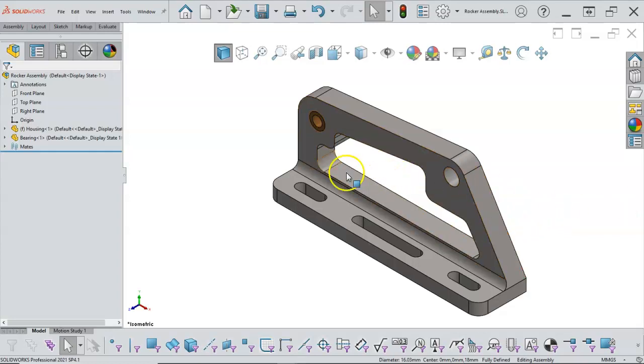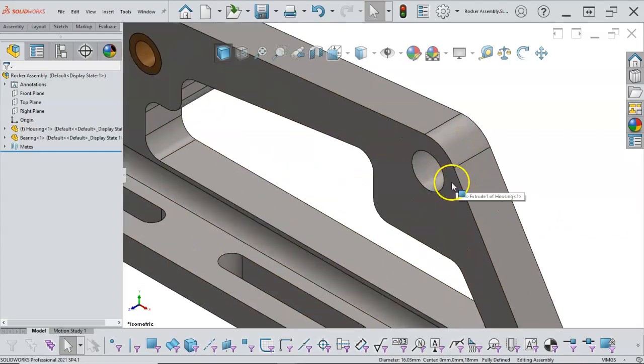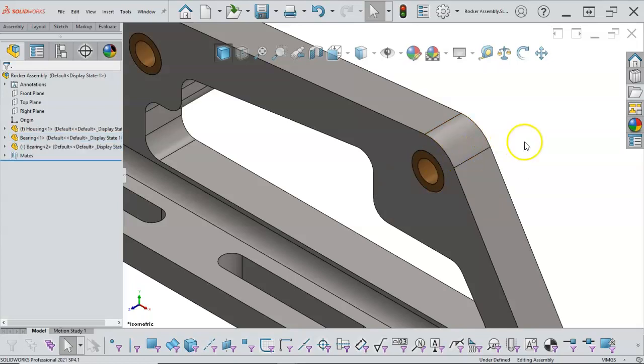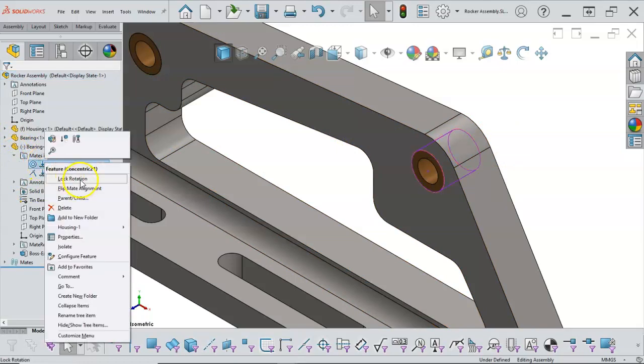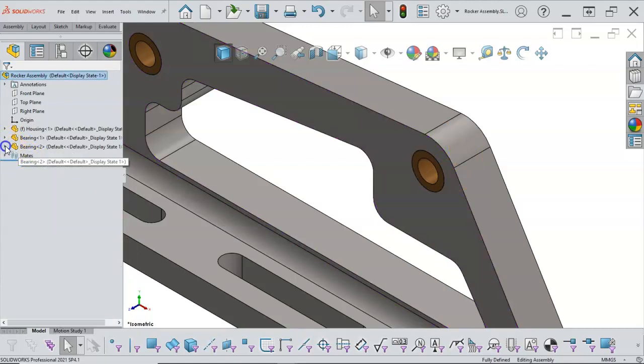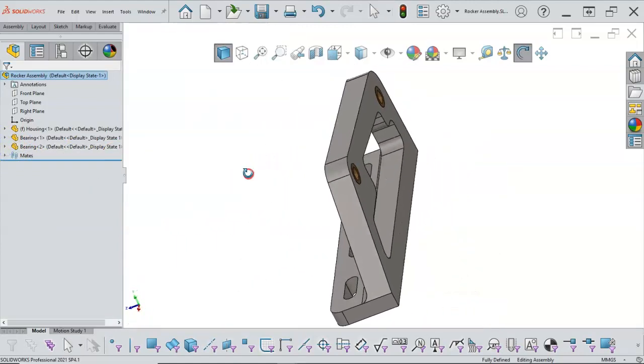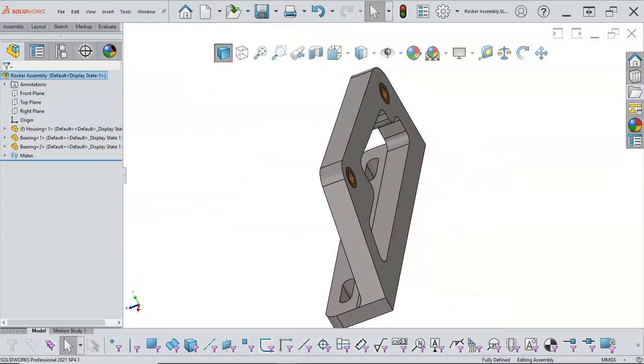just doing a real quick check. All right, so if I hold down the control button and the bearing and drag it to the edge, and this is where contortionist, I actually want to flip this, so hitting tab flips it, and then I can let everything go. Alright, still didn't see the don't rotate, so right click, lock rotation, fills in the little circle, and we're good.